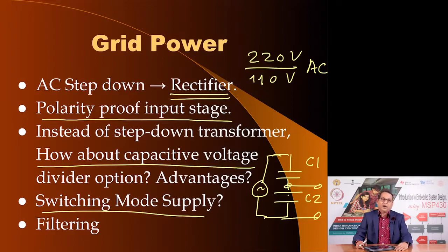These power supply solutions are designed so that they can cater to any supply voltage from 100 volts to 250 volts. They take the AC input and rectify it directly, which would give them a maximum rectified voltage of about 340-350 volts, and then they power a small electronic circuit. That electronic circuit produces a switching waveform which is in the high frequency domain.